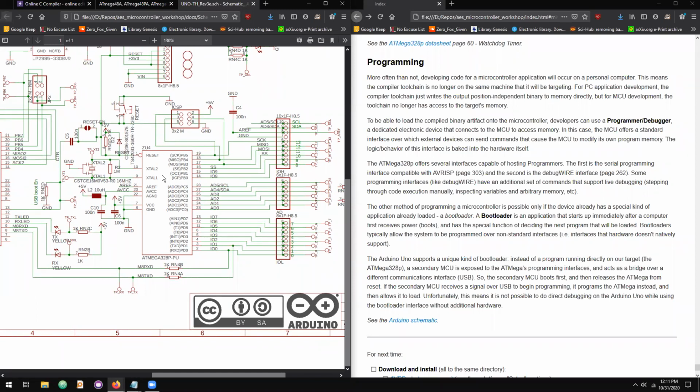and the bootloader says, we can now let you use pins PB0 and PB1 as communication interfaces to communicate your program information, then the bootloader would load as soon as the system receives power, check on those interfaces and maybe wait for a signal. If a signal is not received, the bootloader would then just begin the program that's actually loaded.